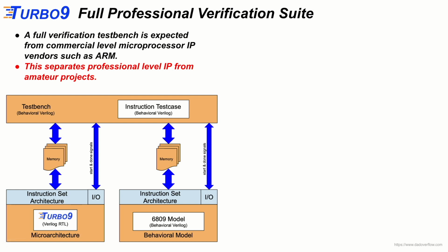generate programs. So we say, okay, we're going to generate a test program for an add instruction. We build a 6809 assembly program, and we push random data into that instruction, and then at the end we jump out and dump everything back onto the stack.